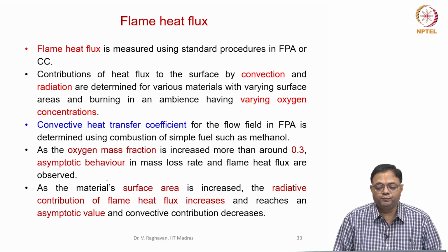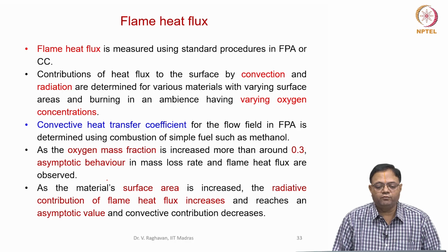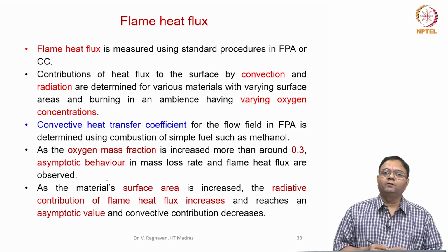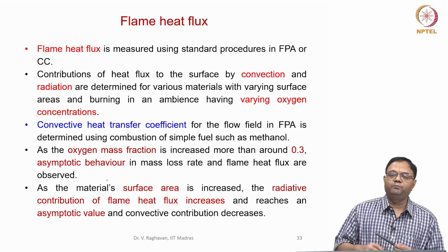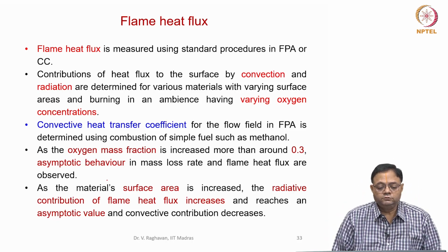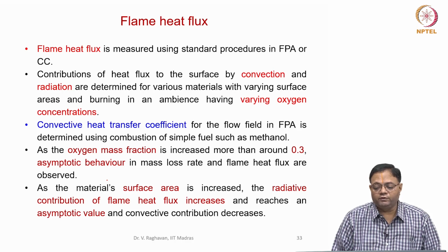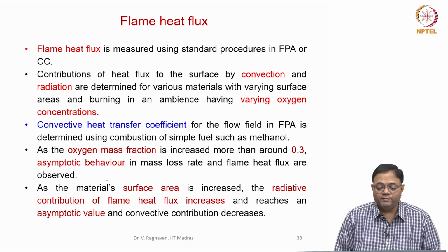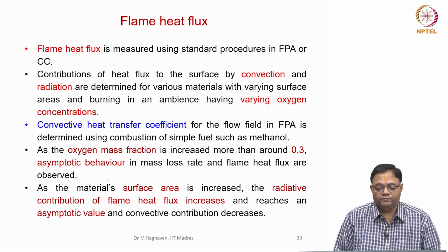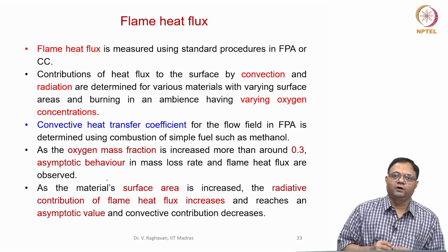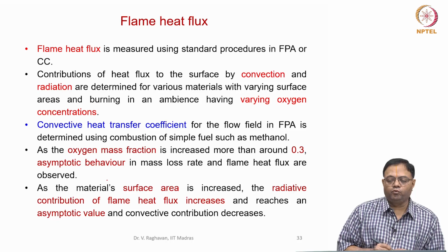Then flame heat flux. There are standard procedures again to find this flame heat flux. As I told you, the flame heat flux is an important parameter, which is the part of the heat coming from the flame to the surface. The contributions to the heat flux to the surface by convection and radiation are determined for various materials with varying surface areas. So, please understand that balance of heat and mass transfer should occur. So, this has to be quantified properly.